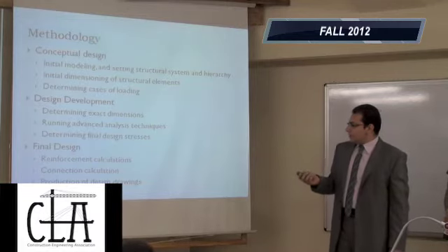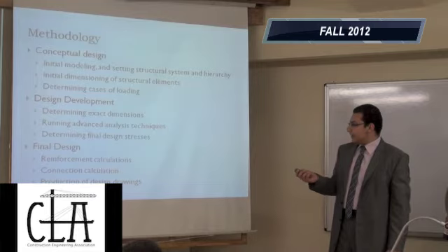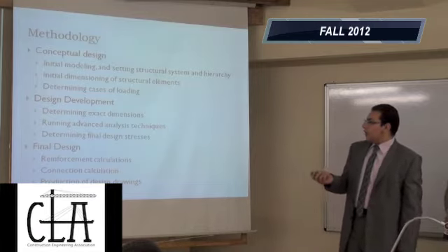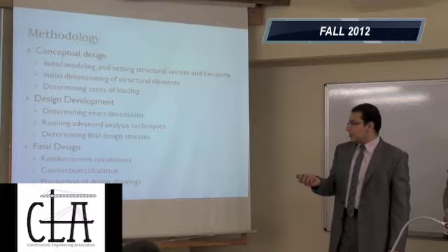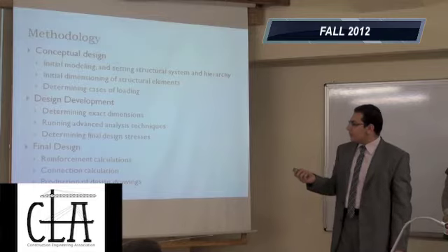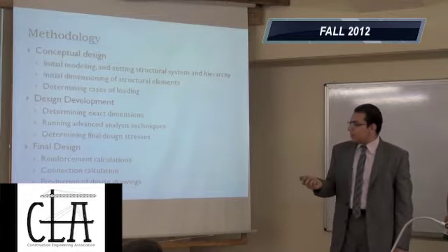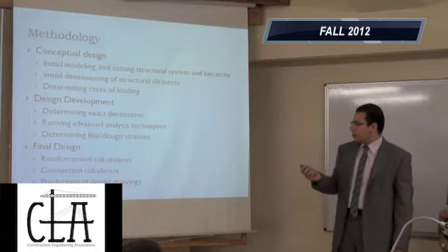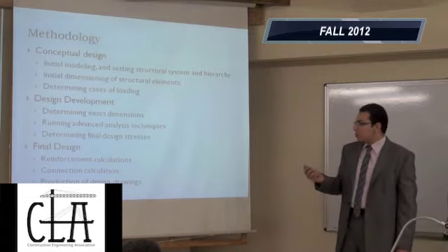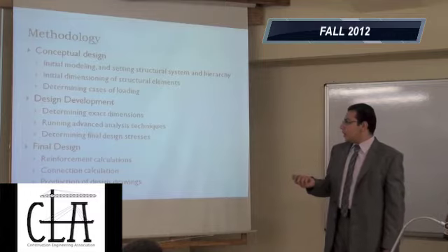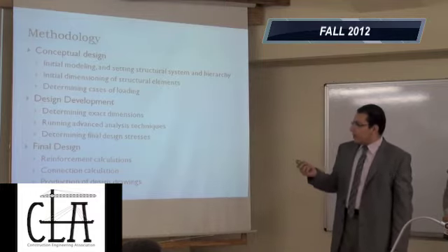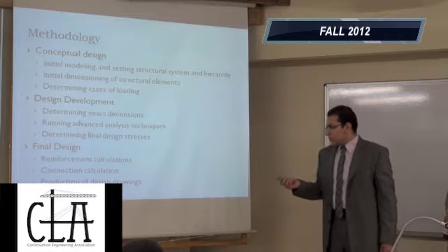In the design development phase, we are going to determine the exact dimensions of the sections after finalizing the analysis, and we are going to run some more complicated analysis techniques, like using area elements for modeling the behavior rather than grillage or fishbone models. And also we are going to determine the final design stresses after the end of the design development phase.